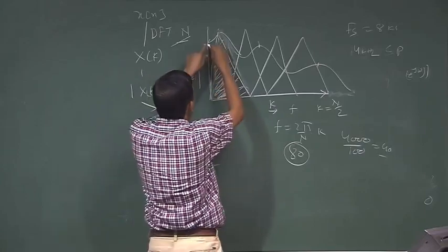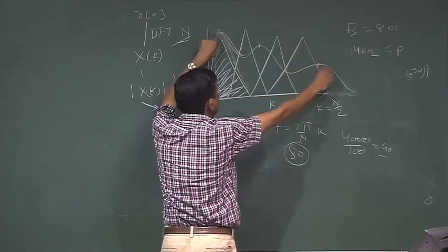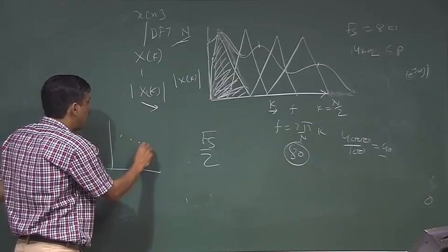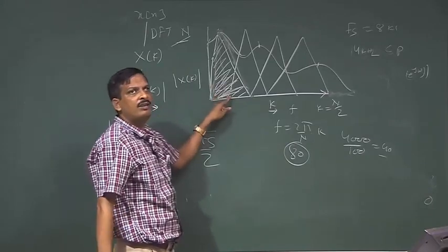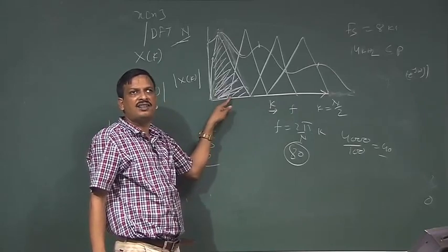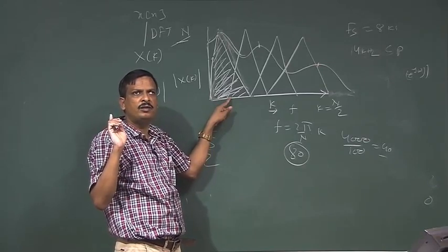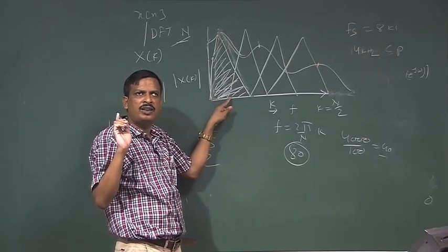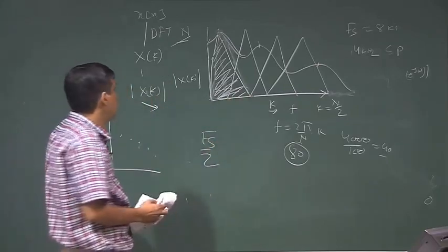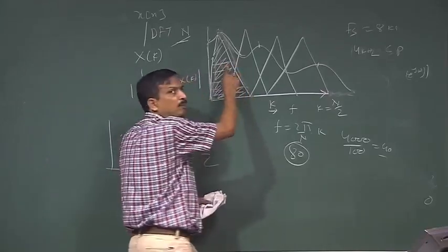So, instead of taking the whole spectrum, I am taking 80 points of the spectrum and finding the Cepstral coefficients. I can treat that as a signal passed through the inverse DFT, and Cepstral coefficients will be generated. Okay. So, information is reduced.